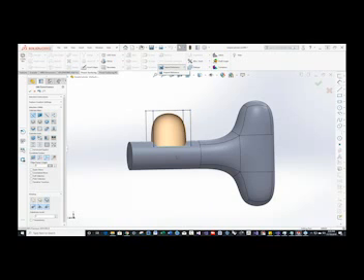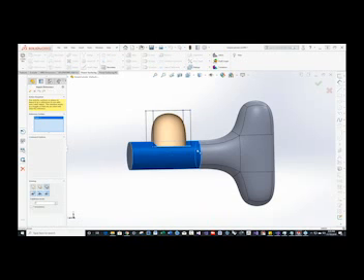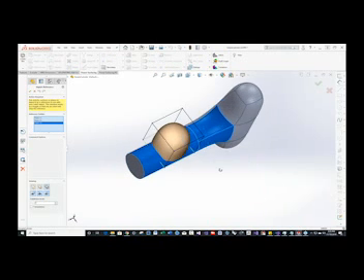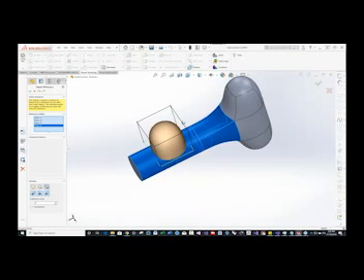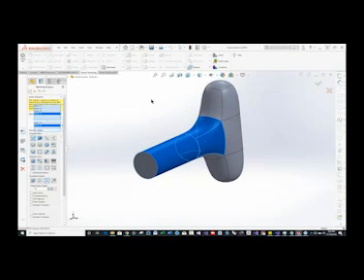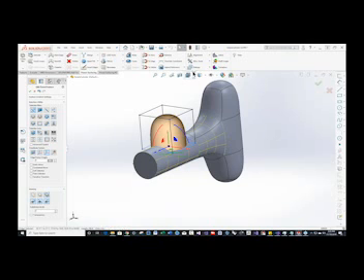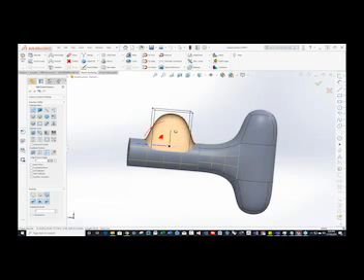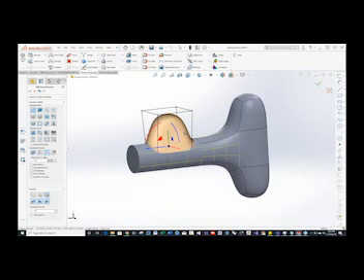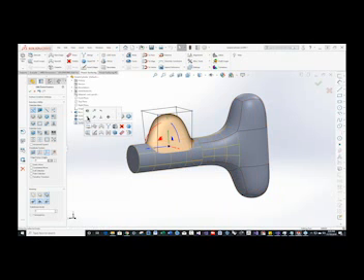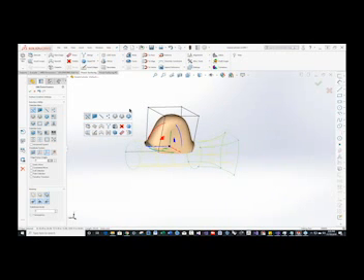And I have to import the reference again. Oh, I'm going to hit the button actually. So if I decide I want to go over here, I could always pick these surfaces as well. I'm going to grab those edges and I can say to face. And so then we have it constrained to the face. It's still a little bit hard to see. So, if we went down here, we could turn off the surface knit so we could see what's going on.